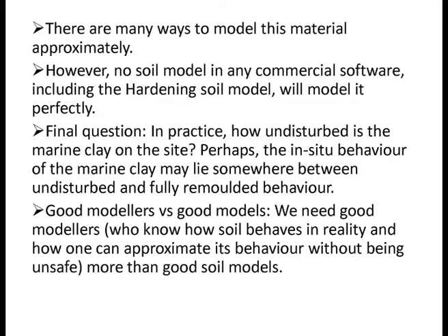Of course, there are questions like, some people will ask, how undisturbed is the soil on the site? Nobody will know. But I would imagine that the soil on the site is so big, the mass, that even if you put a huge crane on top, it will probably not be disturbed very much. Of course, when you drive your sampling tube through, around the sampling tube there could be a lot of disturbance. But this is where you need to use engineering judgment.